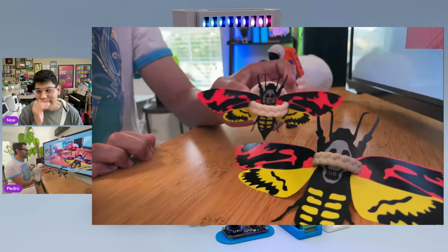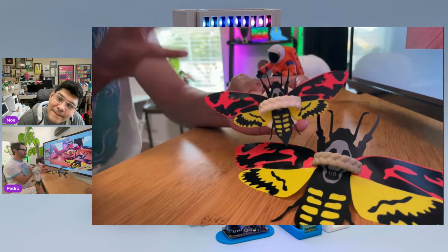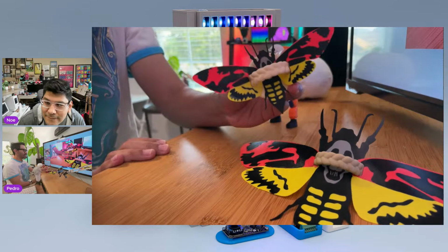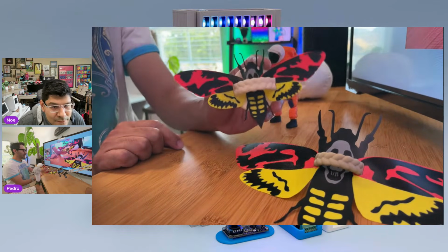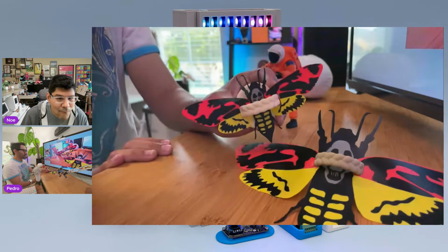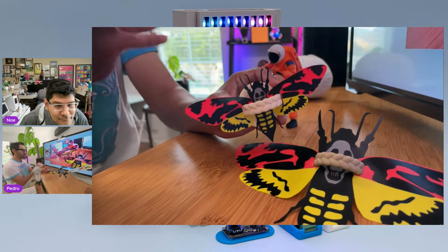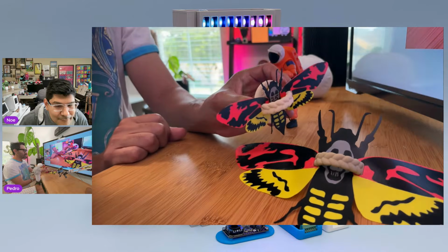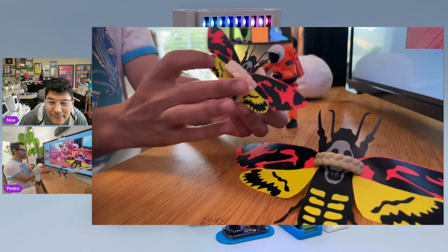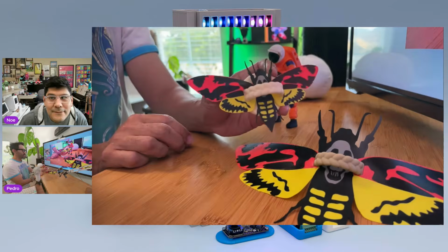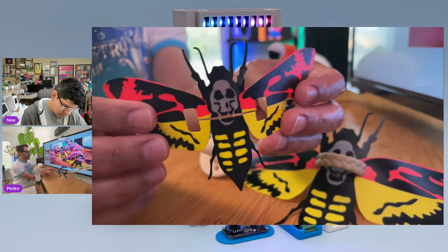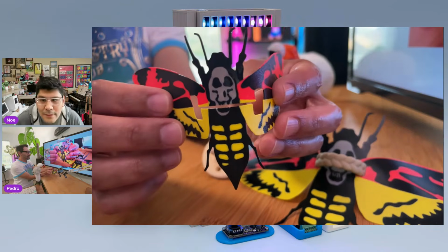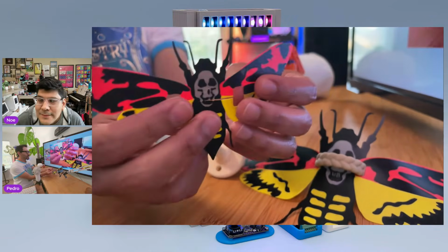So I just grabbed this and traced it inside of Photoshop. Brought it into Illustrator to separate all of the compound paths and combine those, so all the different colors can be imported into Fusion. Did the extrusion and then separated the colors into their own components, so that's all together when you import it into Bamboo Studio to do the color assignment. And it did a really good job, especially with the detail over the skull here. The little teeth are very good, resolving, and then the little cutouts.